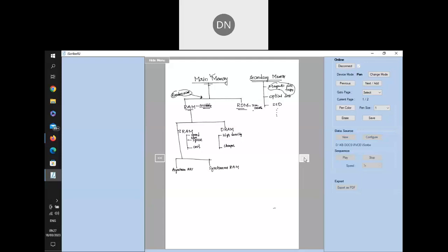Nowadays most of the RAMs used in motherboards or in embedded systems are of the synchronous type only. In synchronous, there is a next category which is an improvement on that, which is the double data rate, DDR SDRAM, which is faster than the normal SDRAM. All the concepts are the same; the difference is only in the clock cycle. Normally, in one clock cycle, one data transfer takes place. That means one edge, either the positive or negative edge, is used for the data transfer. If data is transferred on both the positive edge and the negative edge in a given clock cycle, then it's called double data transfer.